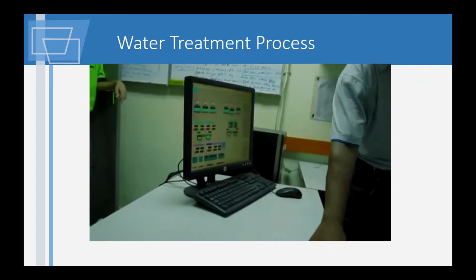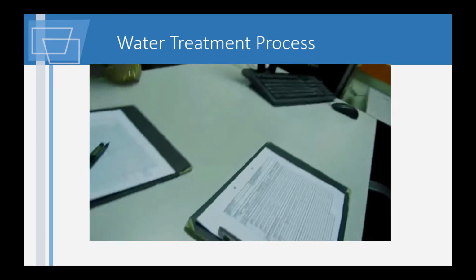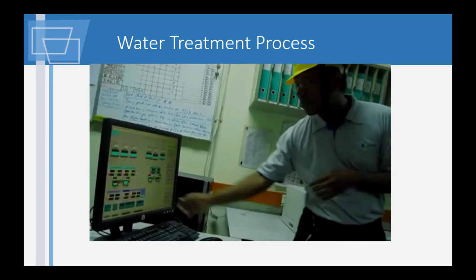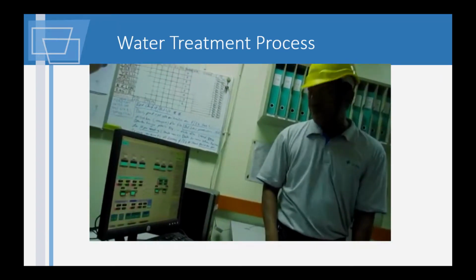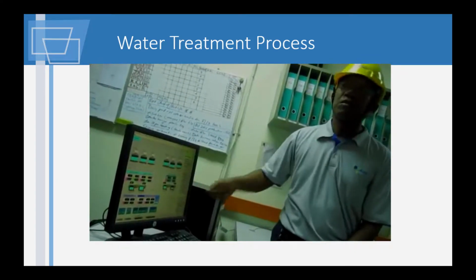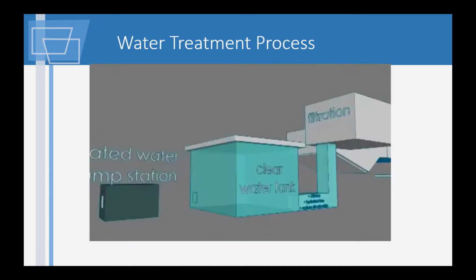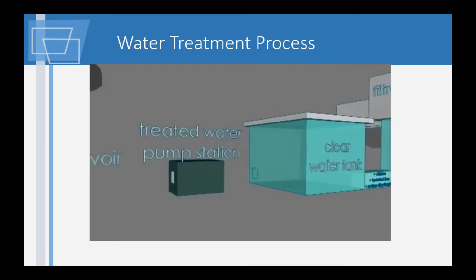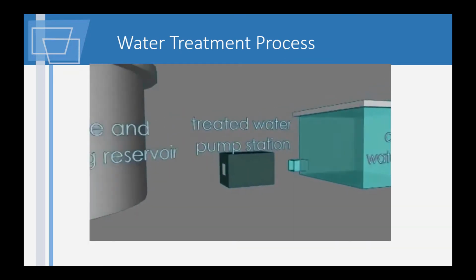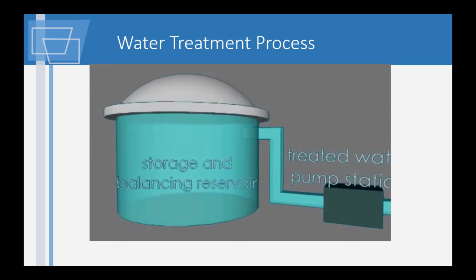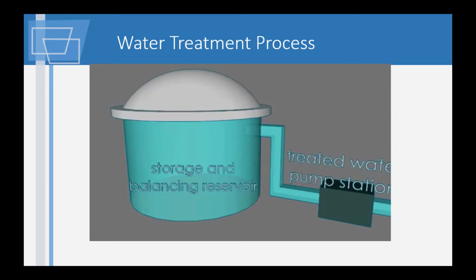Nowadays, the water treatment plants are automatically synced with computerized controllers, which make the task easier for the observation of water level, raw water intake and disinfection process through programmable systems. From the clear water tank at the water treatment plant, treated water is pumped through long pipelines to balancing reservoirs with sufficient height for distribution by gravity to service reservoirs in various demand centers.